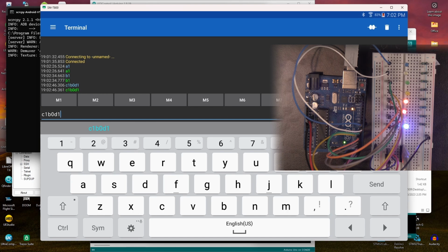So the point there is that through the serial communications, you can just simply plug in something like a Bluetooth module, and I've just connected that to pins 0 and 1 on this Arduino Uno, and now I can send commands to it. So I could very easily, again, if it was in the field or remote or off in a cupboard somewhere, just plug in the Bluetooth module. Obviously, you need to have the wiring there for it, and then I can interact with it and test wirelessly, in this case from my Android tablet. And obviously, if you have an Apple device, the same thing can happen. So that starts to open up some really cool things.